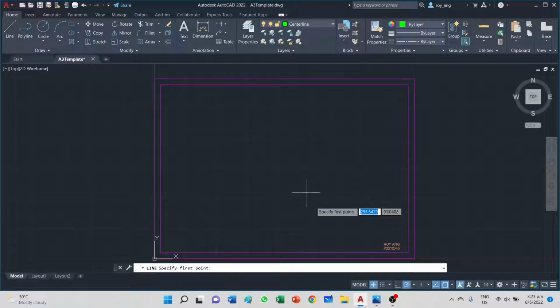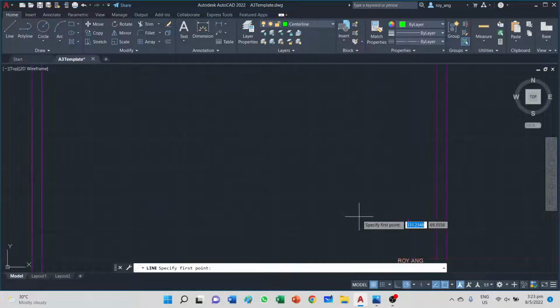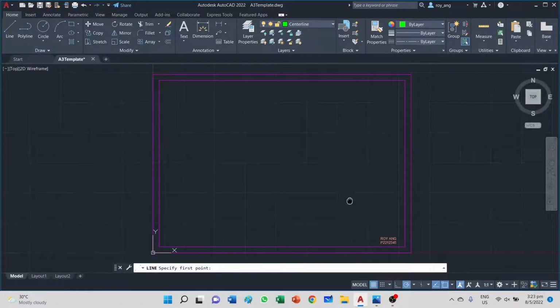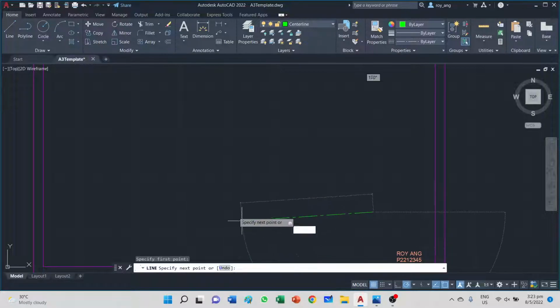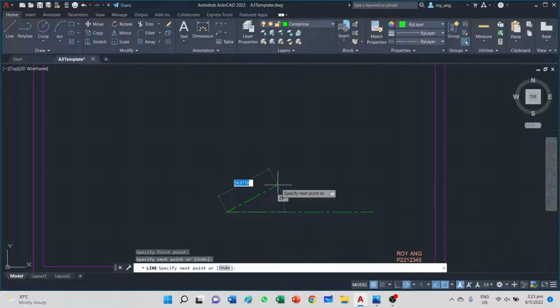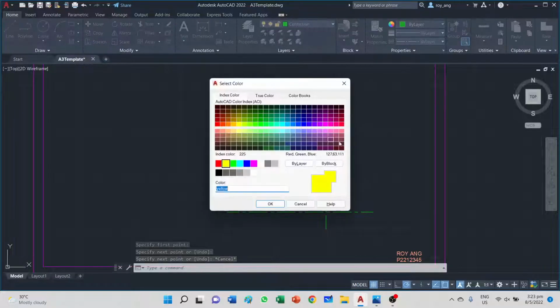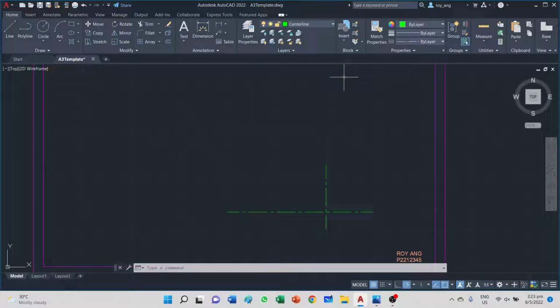So the front view is in this region, end view is here, and plan view is here. The reason why I want to start with the front view is so that I can show you how it's actually okay to draw halfway and then stop in between. I'm going to draw a center, and I'll start off with the circles. You always go about drawing the features, meaning the lines or the outlines that are given very distinct, and you want to draw them first.